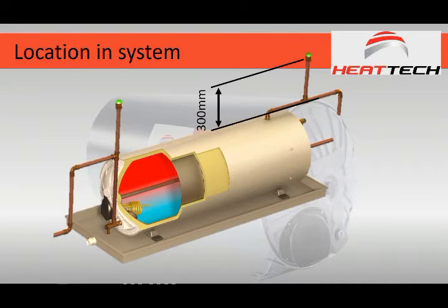Okay. As you can see on the picture, I don't have to go much further than that, but it's interesting to note that the start to open pressure is 300 millimeters water column, and the standard actually requires a vacuum breaker to be installed 300 millimeters above the fitting. I also want to note at this stage: don't only look at 10254, the standard for geyser installations. Also look at 10252 part 1, the parent standard for all installations. Some requirements are captured in that standard which are not necessarily in 10254, and everything needs to be complied with.